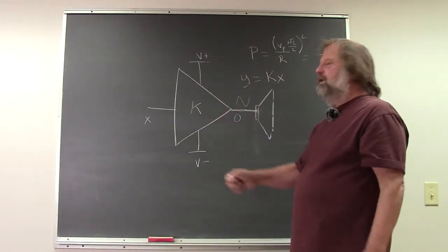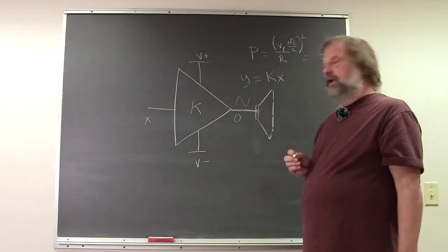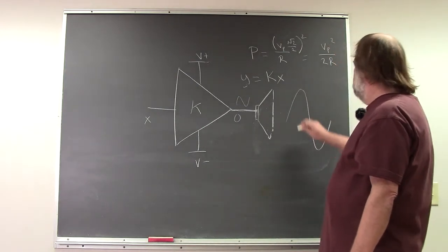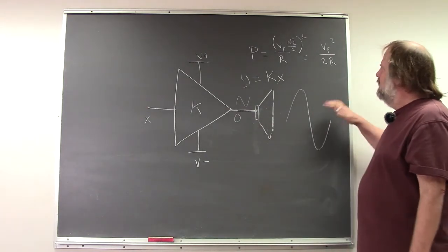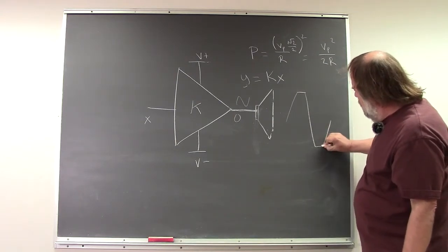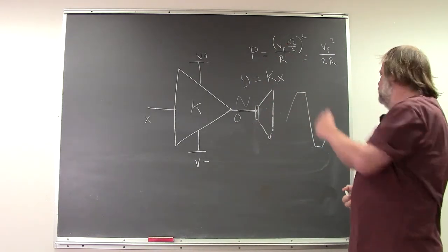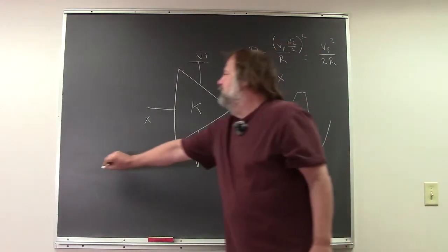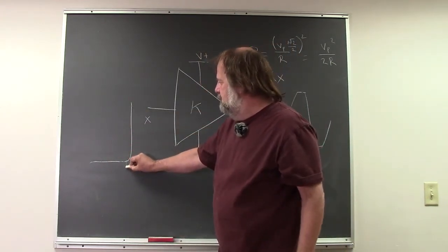So why do we care about that? Well, the one thing that makes any amplifier a bad amplifier, no matter how you built it, is called clipping. Most of you know what clipping is, but I'm just going to explain what really happens. We've got some signal coming in, comes out here. If I put a sine wave in, I get a sine wave. That's good. But as we start running this at higher and higher levels, at some point, we run out of supply rail. Or if there's a transformer, we still run out of some kind of supply rail, and it starts clipping. So when you look at distortion of an amplifier, it's going to be probably pretty low, and then the distortion curve does like that, and that's the clipping point in here.